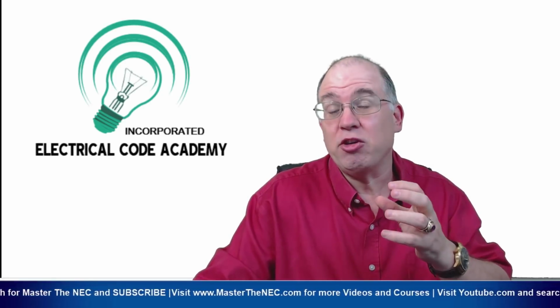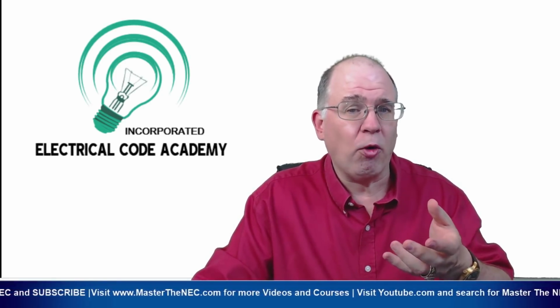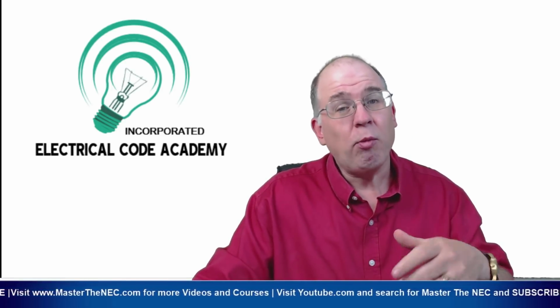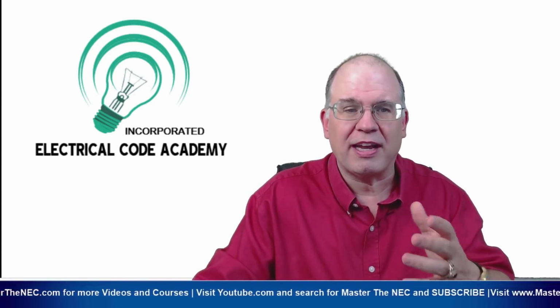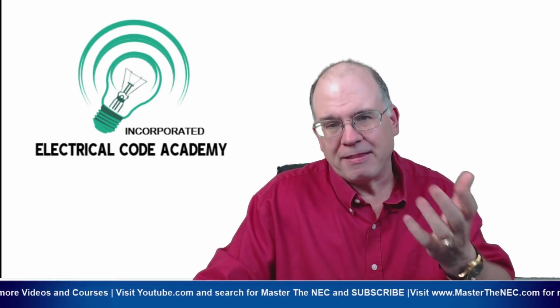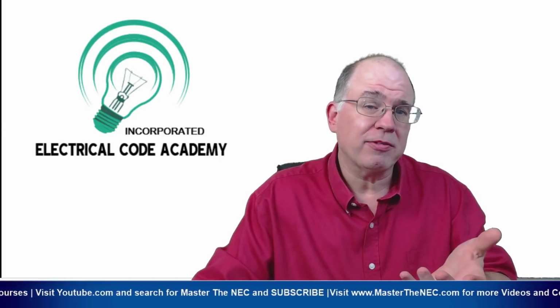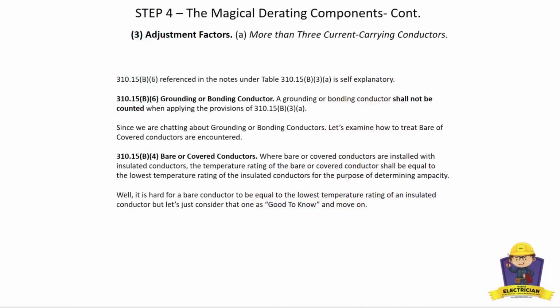Now, once you take it and you insulate it, then you're utilizing standards like UL 83 and UL 44, which are UL standards that talk about how thick that insulation has to be and what type of testing those conductors have to be exposed to, to make sure they don't fail under the test parameters. That's different. But ASTM is what we use when we're dealing with copper. So it's kind of good information to throw out to you.